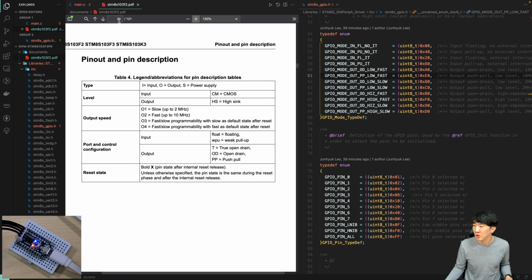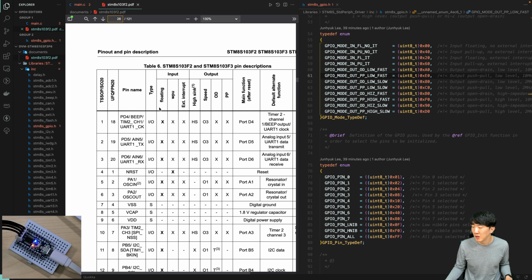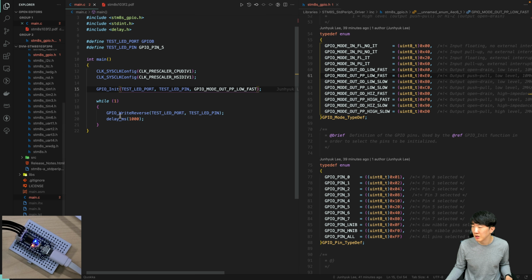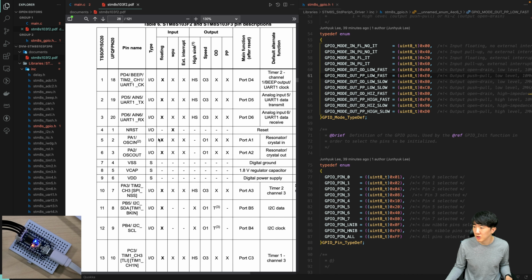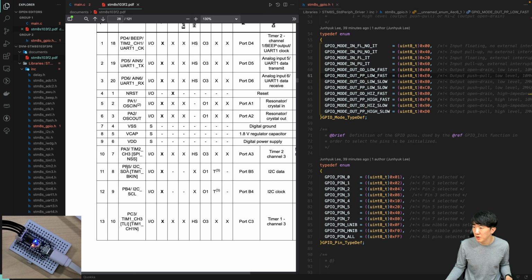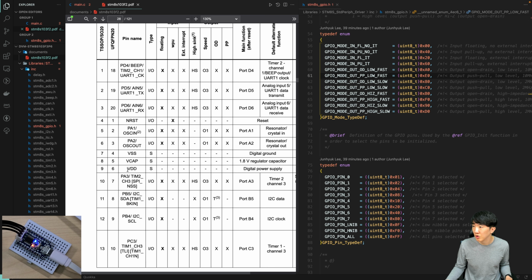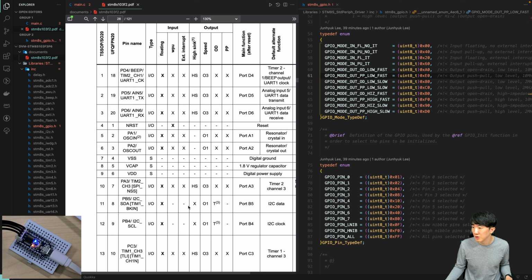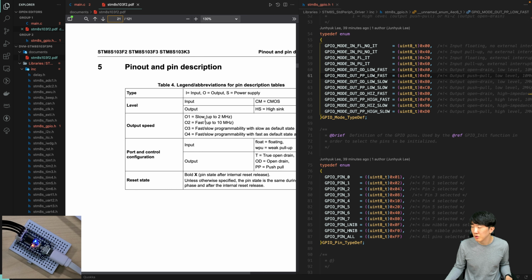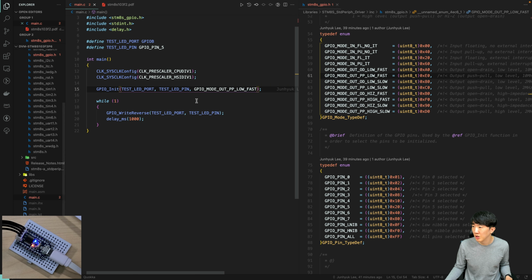So, actually, looking at the pin map for the STM8S103F3, this is the pin map. And the pin I am using from this side is pin 5 of port B. In the case of port B, it's PB5. So if you look at the output side here, as you can see, the speed is at the present moment 5, 1, which means it's slow. And therefore, it is operating at a reduced pace. So I made a mistake. Here, it should be slow, not fast.